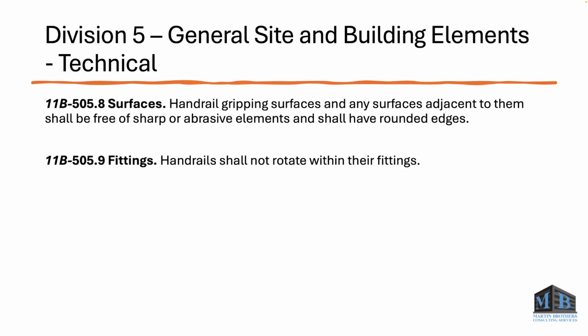11B 505.9, fittings. Handrails shall not rotate within their fittings. So your handrail can't free spin within a bearing or anything like that. It's got to be solid and immovable.